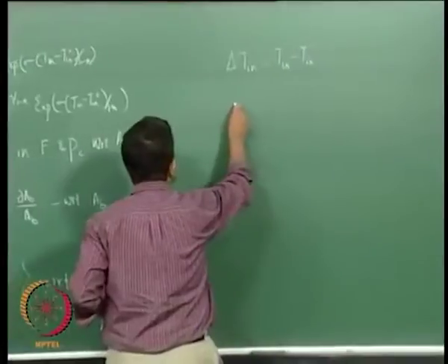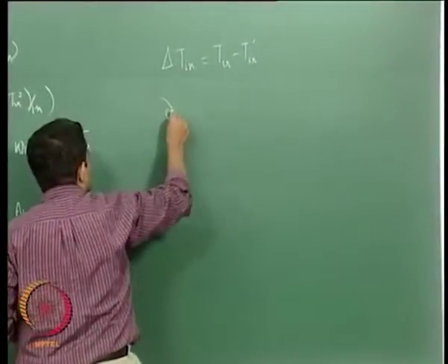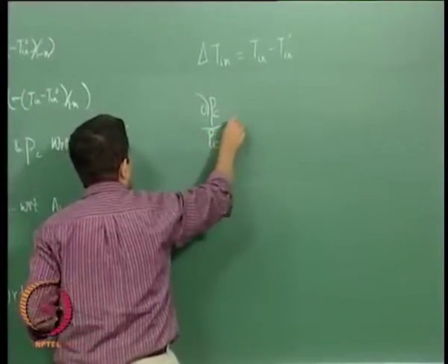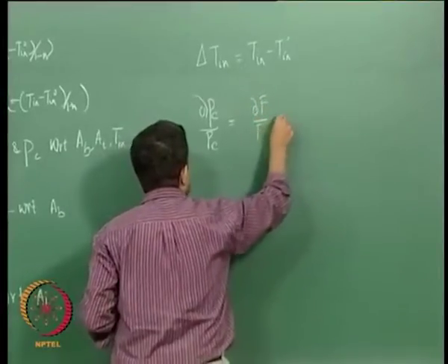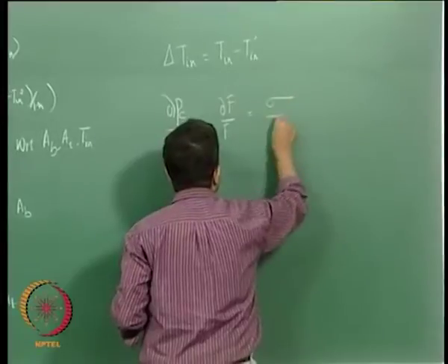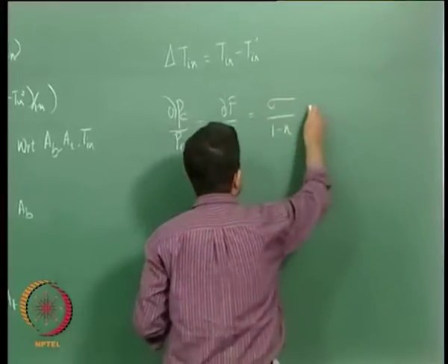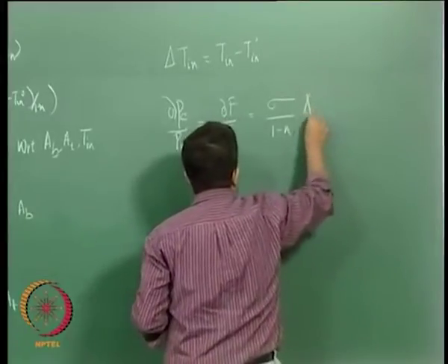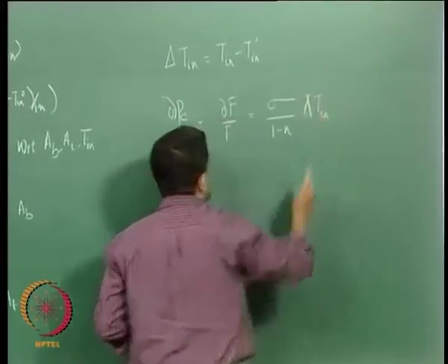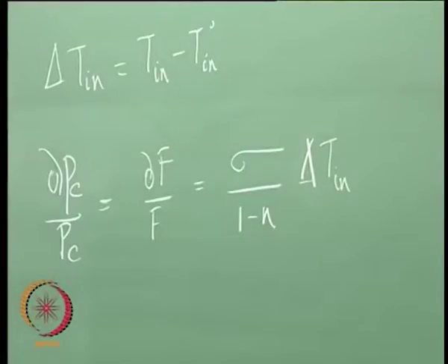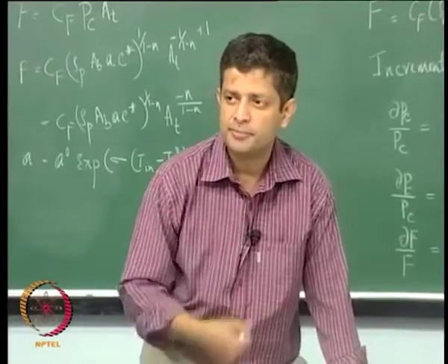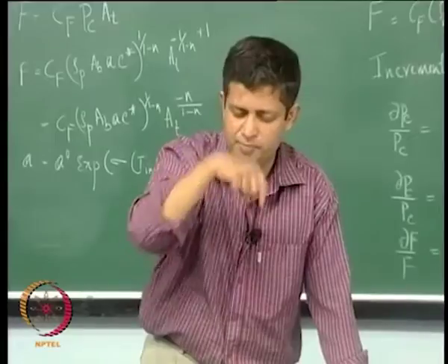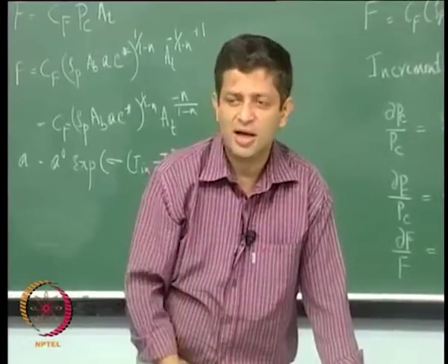So you will get, okay. So we've been able to look at what is the incremental change to chamber pressure and thrust in terms of changes to burning surface area, throat area, and temperature.